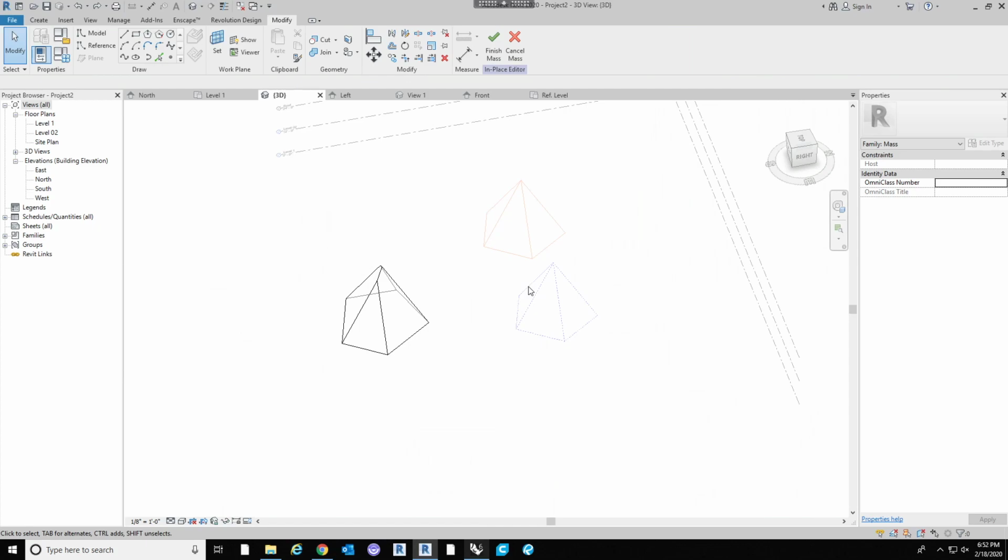It all depends. So if you do run into issues, check the file type that you're exporting. Check the options that you have with each file type, like the default versus the AutoCAD solids, etc. And then check how you're importing it into the file. Some things are just too complex for Rhino or Revit to handle, which is unfortunate, and which is why I highly encourage you guys to try and model your massing. If you do plan on using Revit as your primary tool, model the massing in the conceptual massing environment.